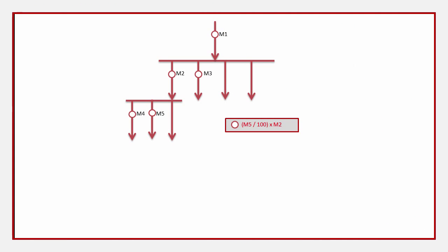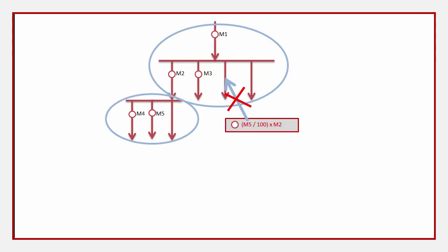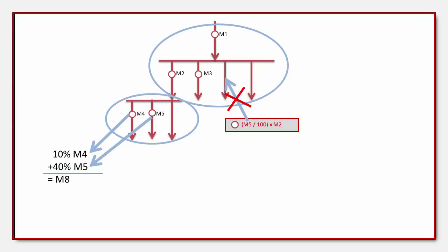And remember, calculated meter points cannot be allocated to the supply structure. Totals and differences for distributions, media, locations or the entire project are created independently by Visual Energy and do not have to be created as a calculated measurement. Cost centers and energy use are intended for and much better at displaying consumption values proportionally. They also do not have to be created as calculated measurements.